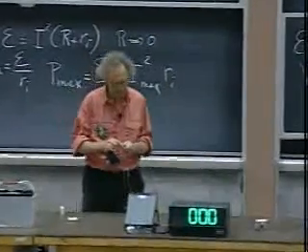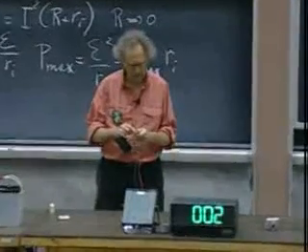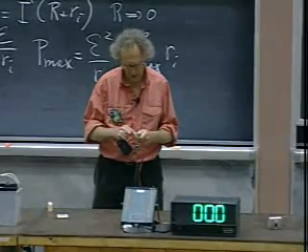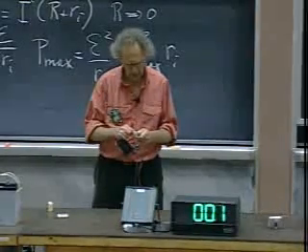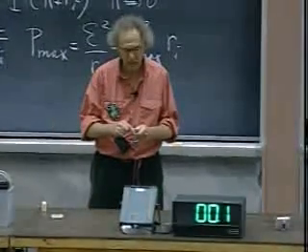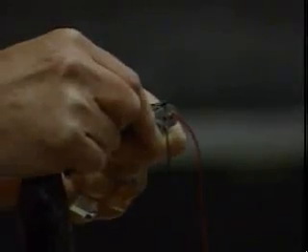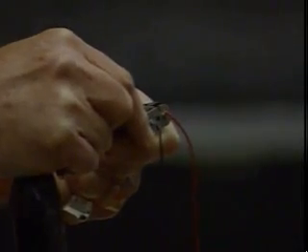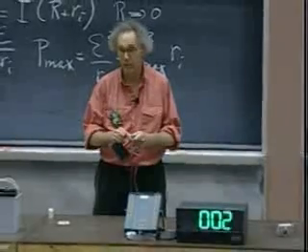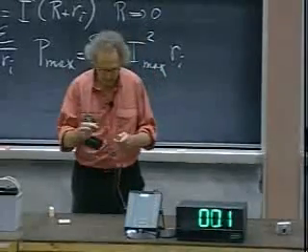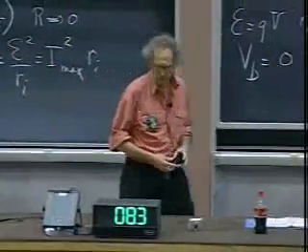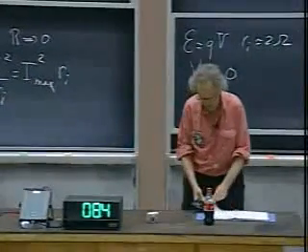I'm doing this now. And you read the voltage. I can see it here. Oh, it is always not so easy with a key to do that. Here, it's very low. Hey, but look at that. It's about 1/10 of a volt. And I feel this thing getting hot. It's really warming up now. And so I'm ruining this battery, which is a terrible thing to do. Batteries don't like that. But when I take off the external resistance, some of that may come back. It may not be permanently damaged. So you see it's already 8.5 volts.